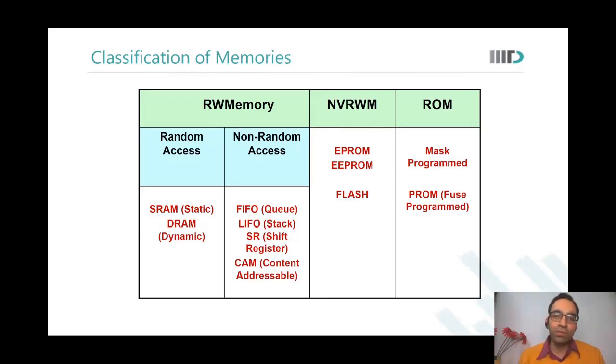Yeah. So what I will do is the voltage regulators on the chip, they always have some calibration bits. I will make my logic in such a way that the information from the PROM goes and triggers those calibration bits in such a way that this voltage regulator now generates only 1.26 volts instead of 1.3 volts, or 1.14 volts instead of 1.1 volts. Okay, sir.